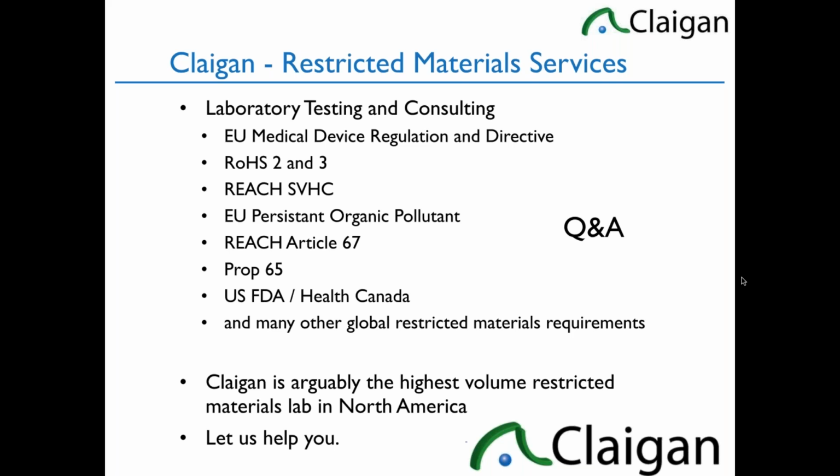It seems semi-arbitrary, but so says the guidance. A consumable with electrical function is in scope. A consumable that is not electrical in nature is not in scope of RoHS. It may be in scope of something else, like the packaging directive, depending. For example, the packaging for the product that's discarded when the product is put into use is not in scope of RoHS either. It's not intended to stay with the product for its lifetime. However, it is in scope of the packaging directive and has its own materials restrictions.